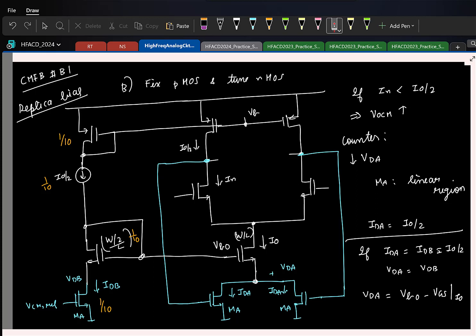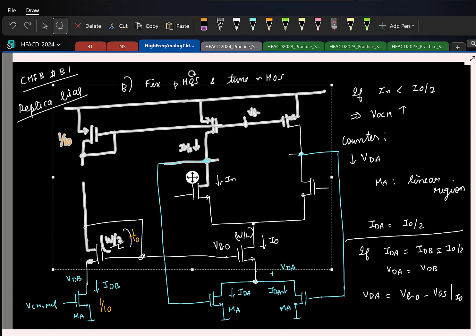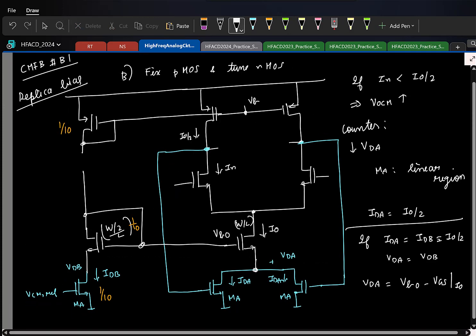Okay. So will we get a reference current available on the chip that's not connected to either of the? Okay, you are asking floating current source like this. That you will not get. So which means you can basically see, this is just an example. I was just showing it as an example. You can basically do some kind of current mirroring and do it, right?